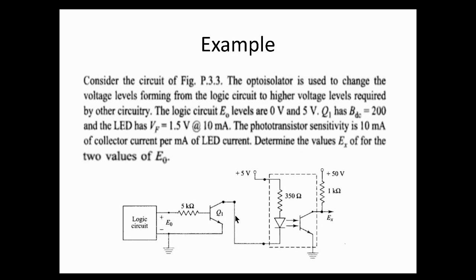I can see 5 volts you're supplying coming out of your microcontroller here, or you apply this 5 volts here. So is it sufficient? You can check, right? There's a 350 ohm resistor in there, right? So what is the current? If we're to work out this current, it would be the difference in voltage, 5 volts, and you'd have a voltage drop of 1.5 volts here.